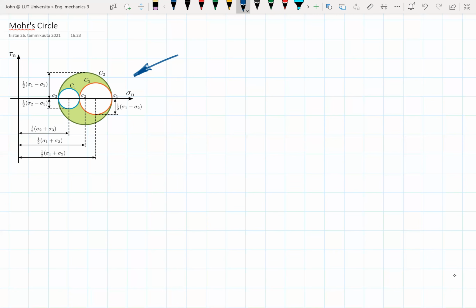However, if you're watching this video and you don't know what a Mohr circle is, we use Mohr circles to represent the transformations between one orientation of the Cauchy stress tensor to another orientation, meaning that using the Mohr circle, it would give us the full information about the maximum stresses, normal stresses, and shear stresses as we are rotating this infinitesimal cube, as we were seeing in the past.